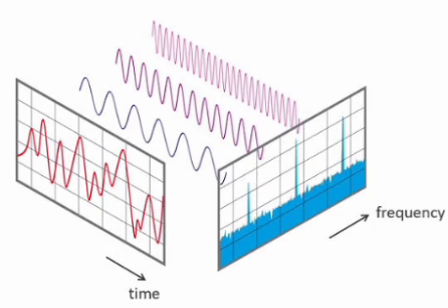The autocorrelation function of a binary rectangular random pulse train x of t equals the sum from minus infinity to infinity of a n p of t minus nT plus t naught, where a n are independent variables with values plus or minus 1 with equal probability, t naught is a time offset uniformly distributed between plus or minus T by 2, and p of t is a pulse of amplitude A and width T. It is given by R x of tau equals A squared times 1 minus modulus of tau by T, for modulus of tau less than or equal to T.